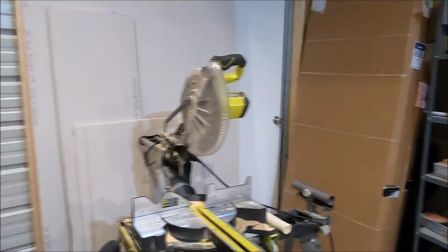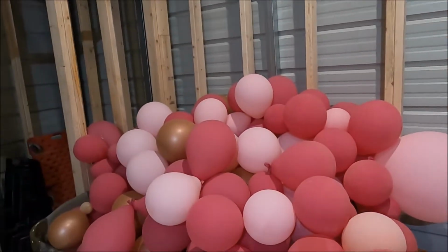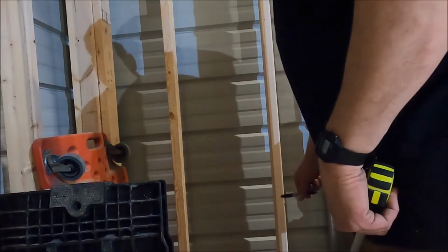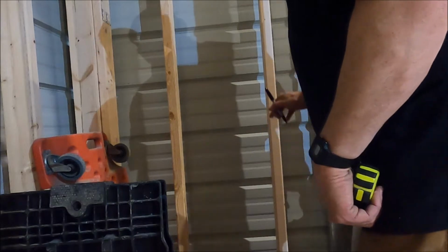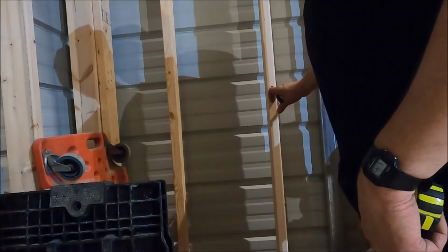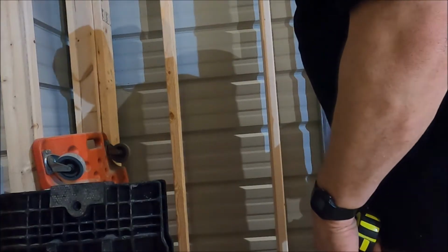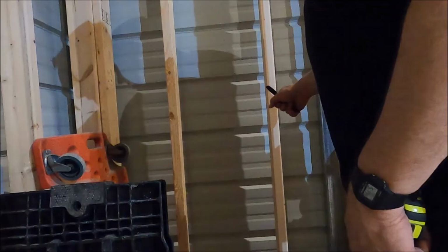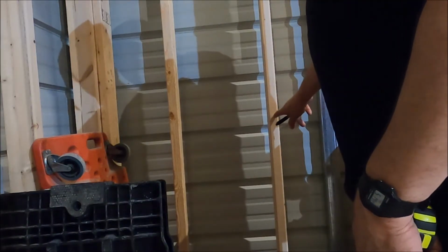In this area, probably isn't happening right now. In the office right here where the desk is going to be, I'm going to put an outlet at 18 inches, and I'm going to come about 40 inches and put in an outlet. So if I need to plug something in underneath the desk, I can plug it in. And then up above the desk, if I need to plug in a computer or something, I'll have this outlet here.